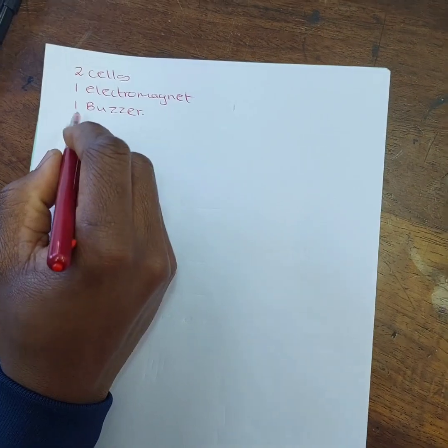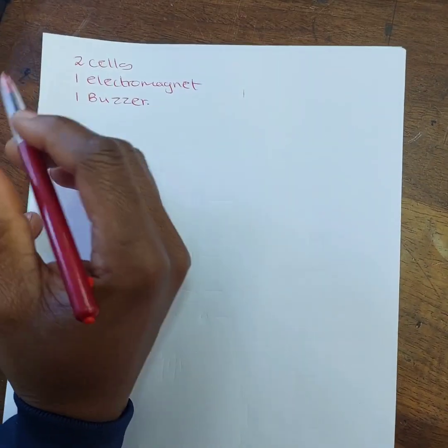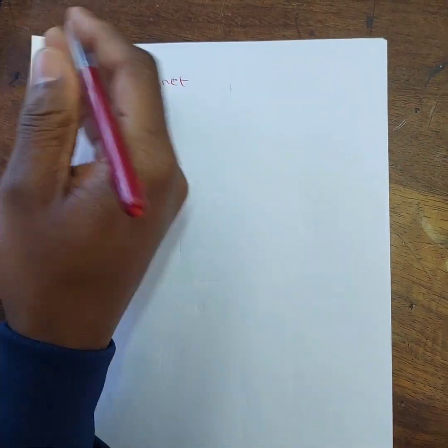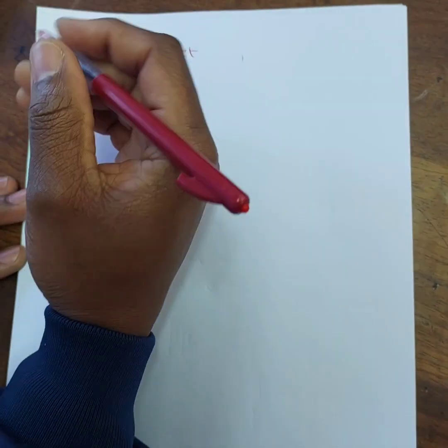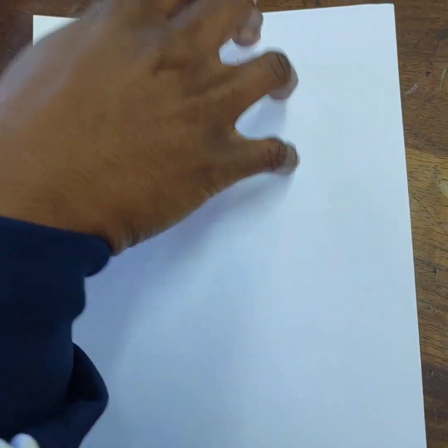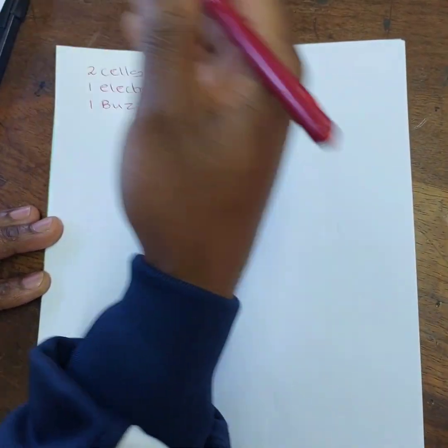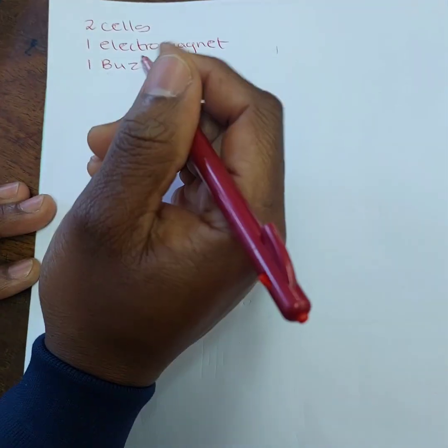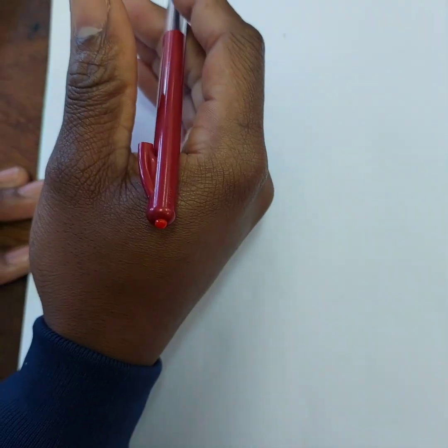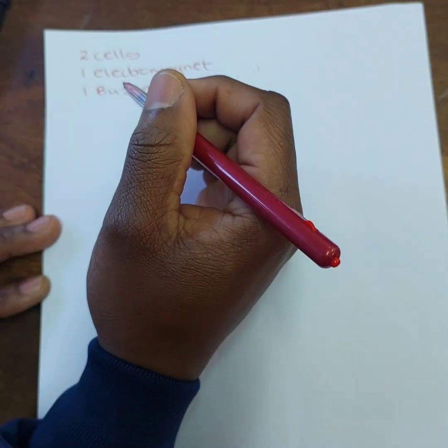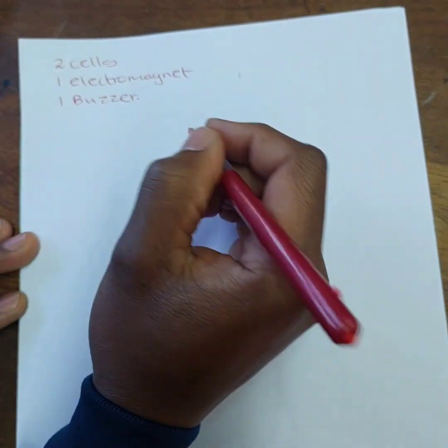The intention of such a circuit is that when the circuit is switched on, it's able to report by making a sound. That sound will indicate that the electromagnet is switched on, because we cannot see whether an electromagnet is switched on or off. We either add a bulb, which is the most common one. In this case, I'm adding a buzzer, but that will be an unfavorable situation because you will be working with an electromagnet and listening to a buzzing noise, which is not good for anyone to work around, but I'm just doing it for demonstration.